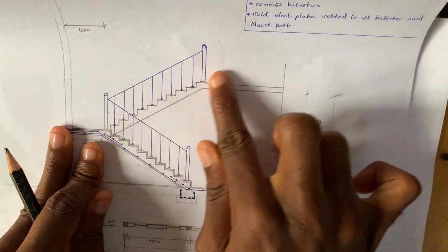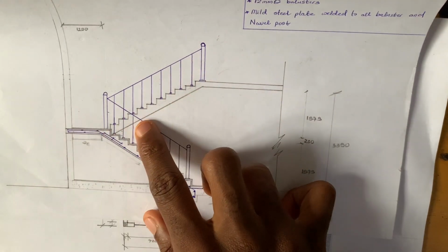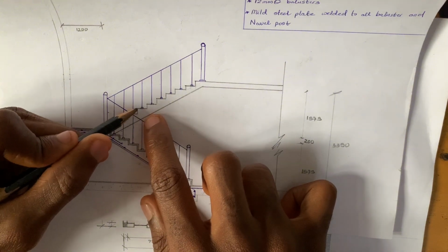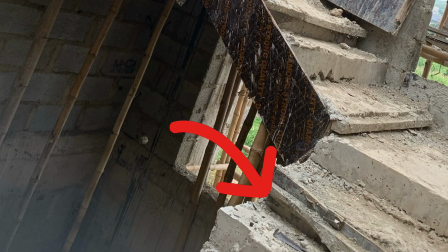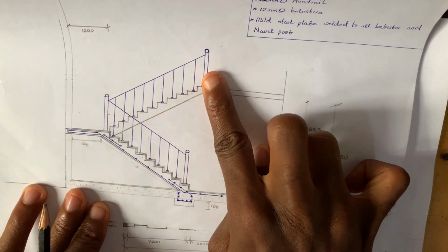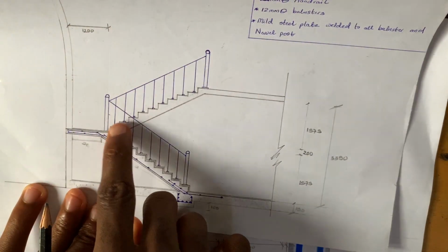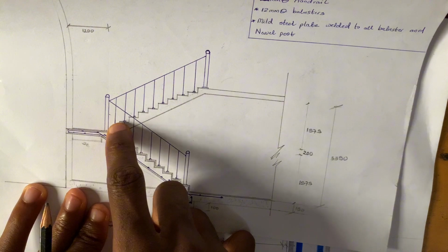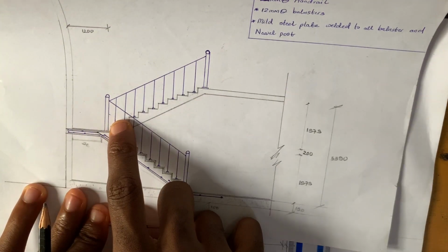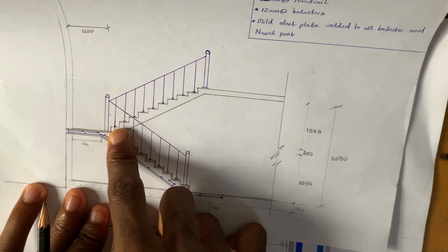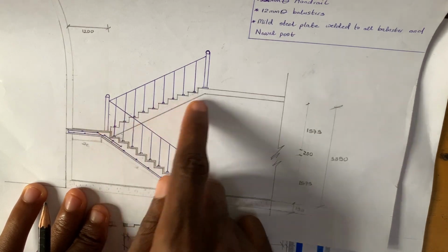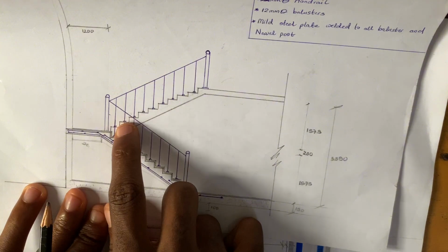So now doing that, plywood, like I said before, is going to cover this, what? The side of the staircase. So now we need another plywood to demarcate the what? Risers here. So after you've gotten plywood covering here, plywood inside is going to demarcate the what? Risers. And we need to measure for that formwork, or for that wood that will give form to the risers.